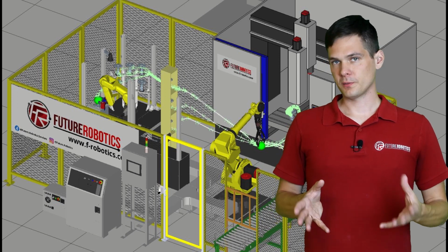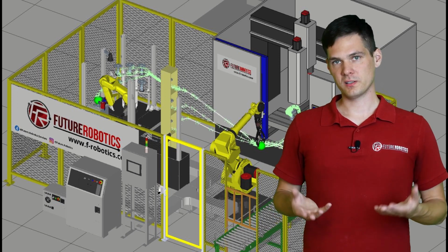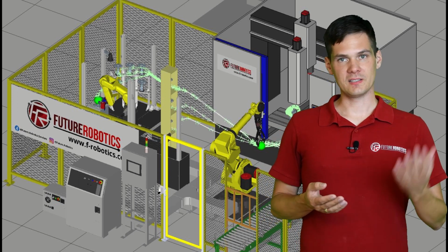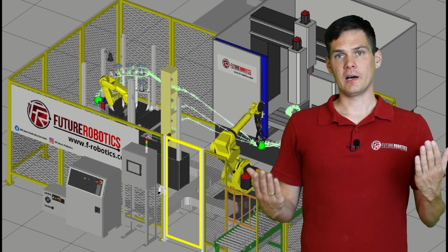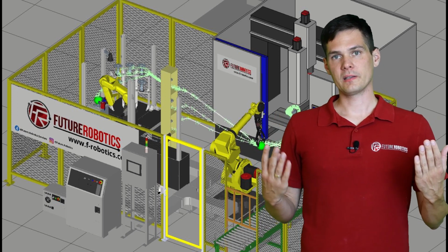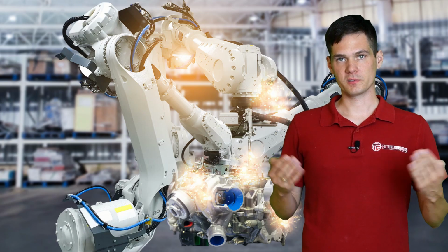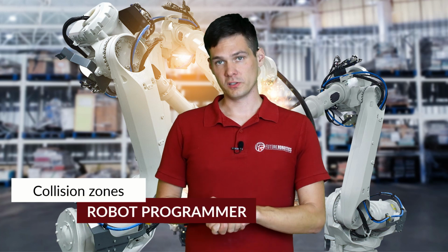If we're talking about different programs that the PLC will not send at the same time, then yes, you can forget about the collision zones. Let's say that one robot is running PNS1, then the other robot can run only PNS1 or nothing else. So you need to worry only about the same programs. The question for you is what type of programs you're running, how your robots operate, and can the PLC send only one type of program to all of the robots, or can it send any program to any robot. Then you need to determine whether or not you need a collision zone.